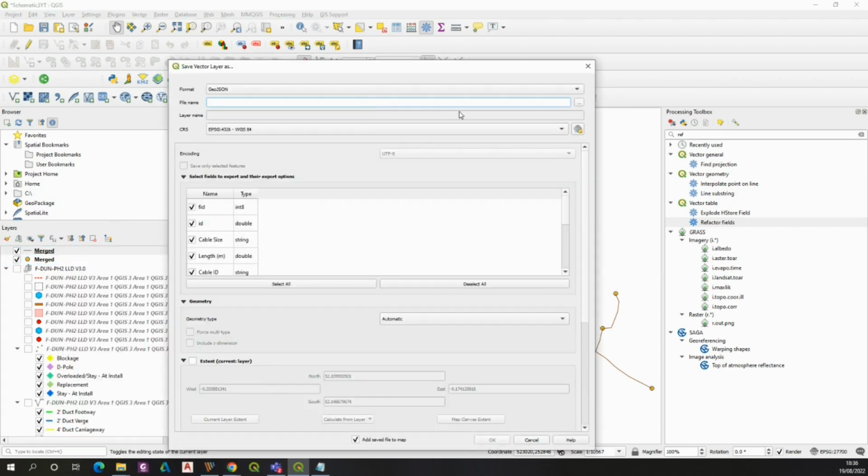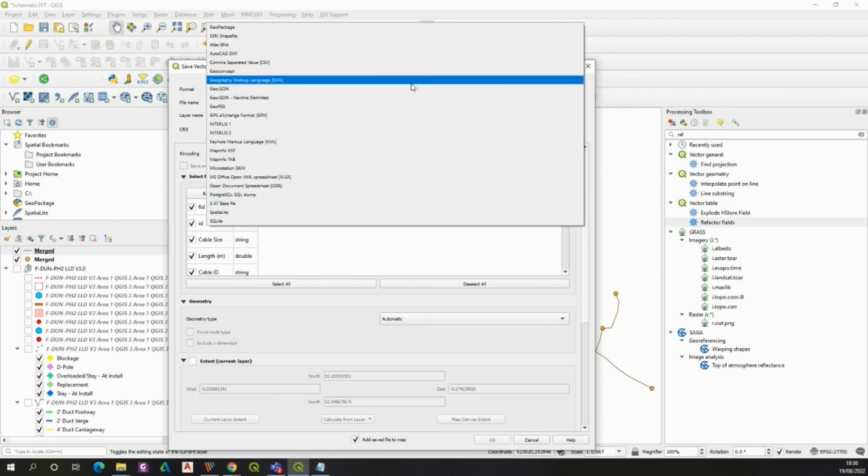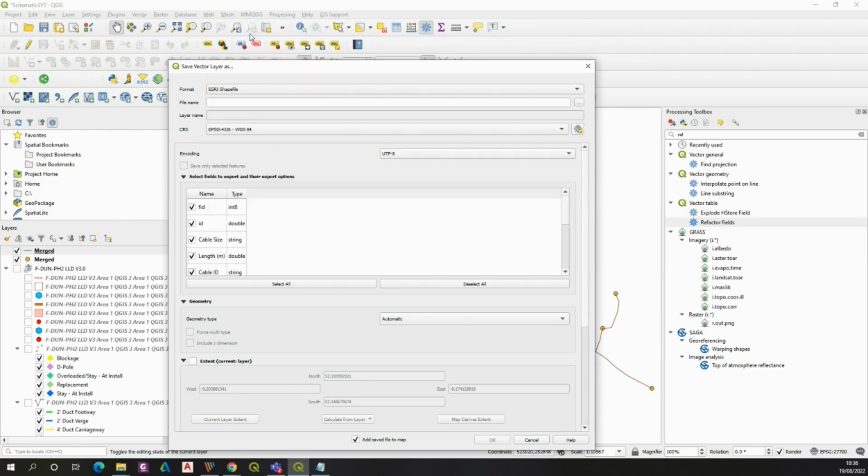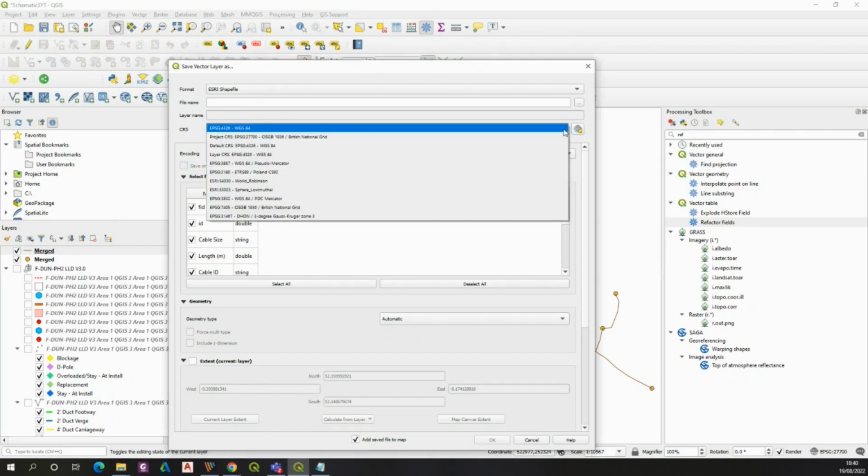Because GeoJSON throws an error. I don't understand enough why it happens like this, but I discovered that the safest method of saving remains shapefile. Shapefile cuts down the length of columns to 10 characters, but the layer column should be still fine. So before we choose the name of our file, it's good to select the coordinates first, because if we stick to the WGS84, the units will still come with degrees, because this coordinate system is general for the whole world.